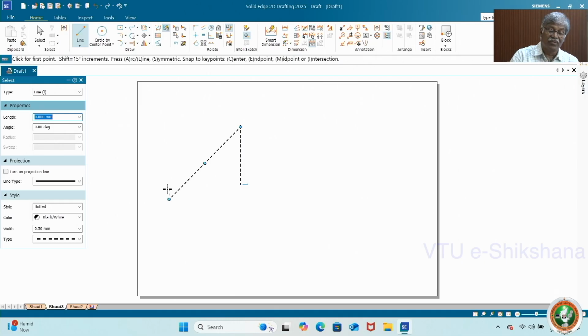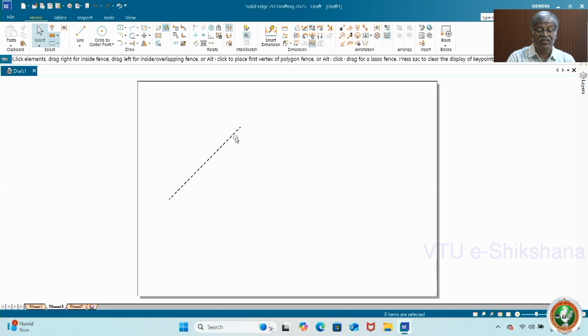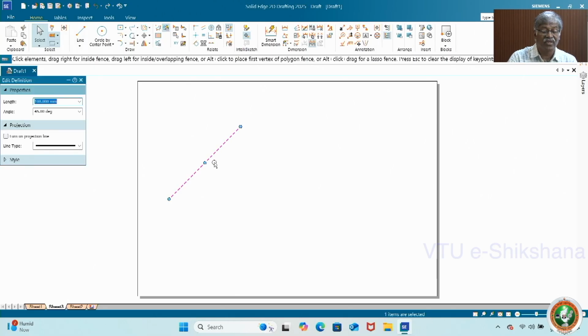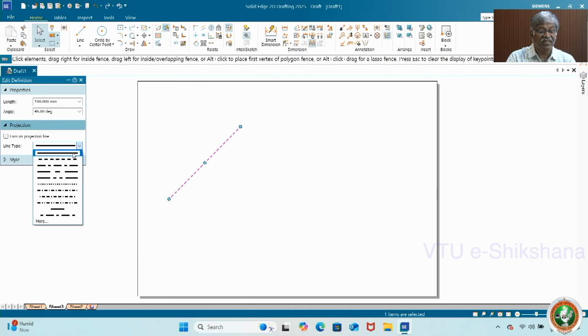So suppose that you want normal line, but you got the hidden line. What to do? You can always modify this. And also I have extra line also. I have made one more click, so that's why it has come. Now, if you do undo, this will go. The extra thing will go. Now I want to change this to normal. Yes, you can select. See here, this is select command. If you select, then just change the type.